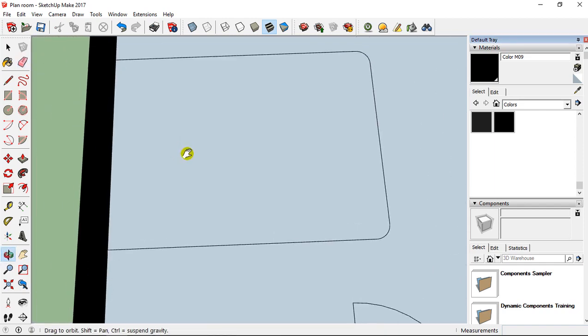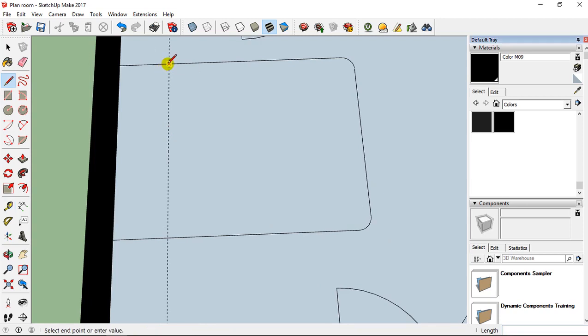Then I'm going to add the pillow and the cover, the blanket. So I take, for example, the tape measure tool, and here I can go on maybe 40 centimeters, like that. And I can add a line. Then I can add another guide, and add a guide here just 5 centimeters, like this.